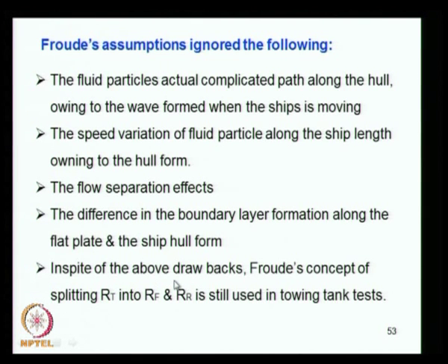But in spite of all the above drawbacks, Froude's concept of splitting RT into RF and RR is still used in towing tanks. We are yet to find a better approach in predicting the total resistance from the model test. So, in spite of all these drawbacks or limitations, we still continue to use Froude's concept of estimating total resistance from the model tests conducted in a towing tank.